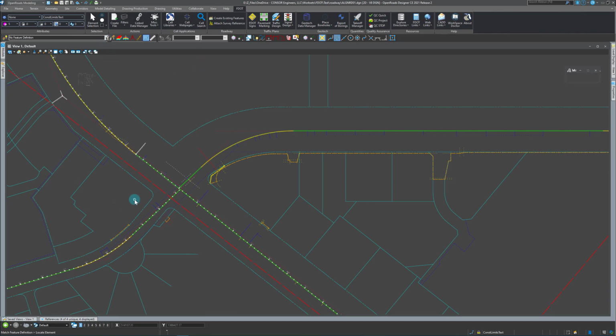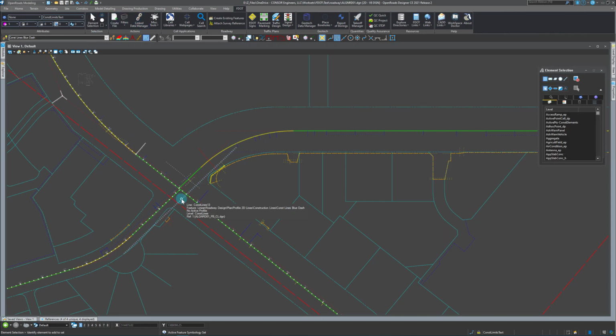The first thing I usually do is start laying out some construction elements. So I have this construction element down here that I'm essentially using to set my bearing through this intersection so that both of my streets line up. Essentially all the lanes line up, and that was one of the challenges of this project, to make sure this intersection lined up.